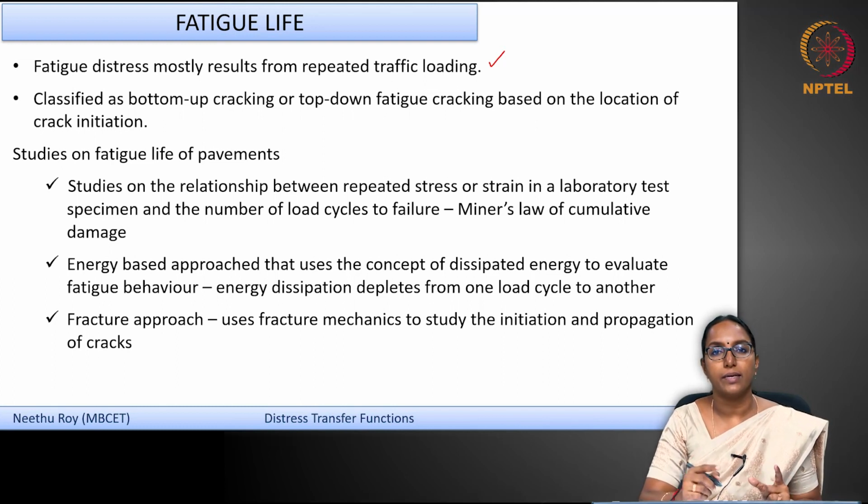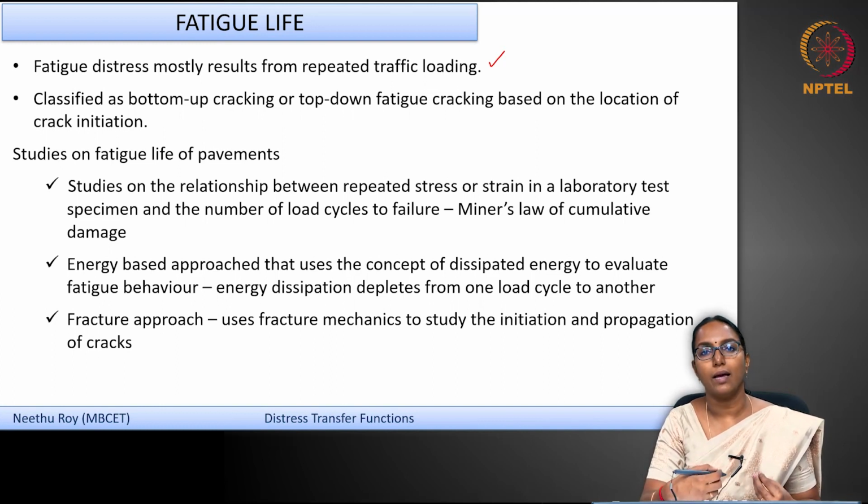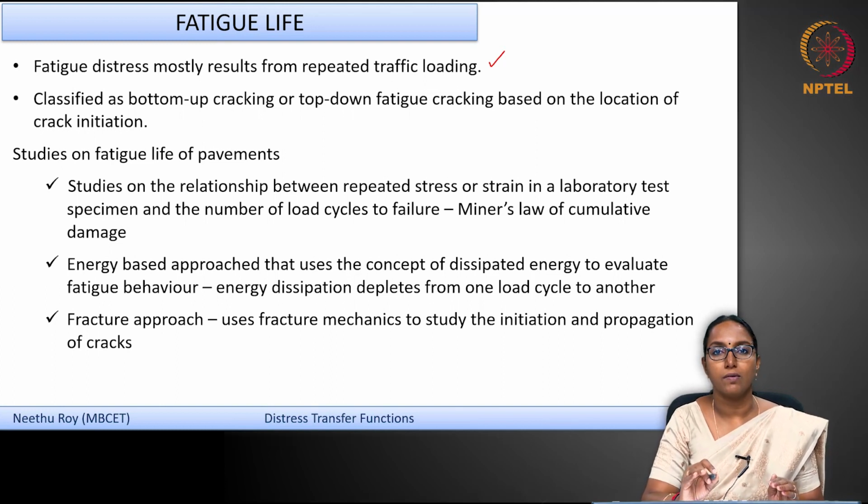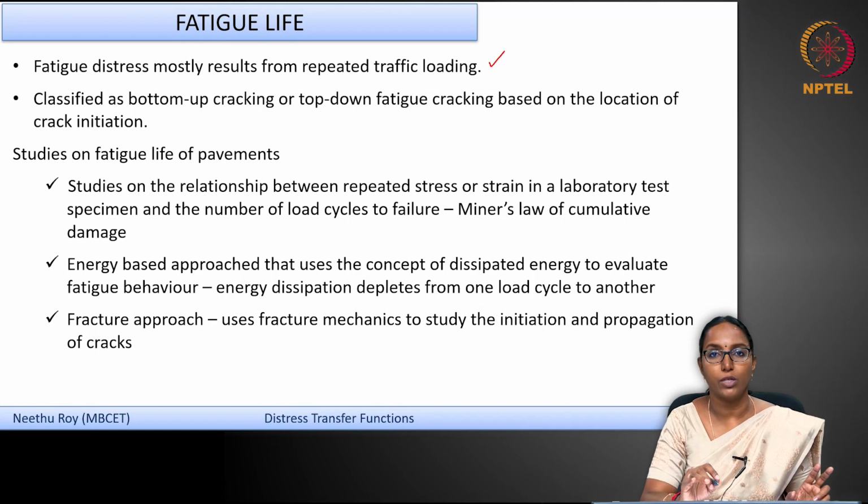Now, how do we study this fatigue cracking? This cracking, or the fatigue failure that happens in a pavement structure, doesn't happen all of a sudden. This is something which happens over a period of time. And this essentially happens because of the fatigue resistance, or the fatigue characteristics, of the bituminous layers.